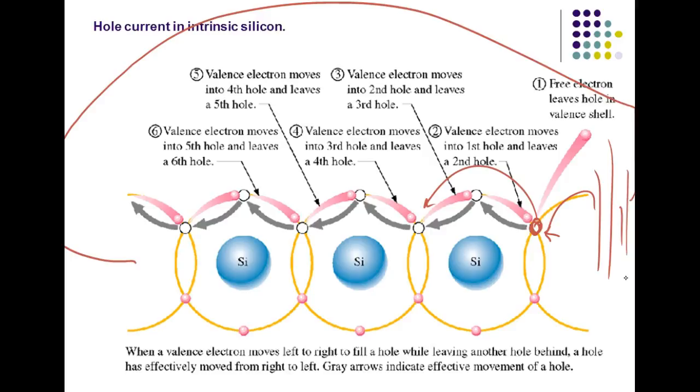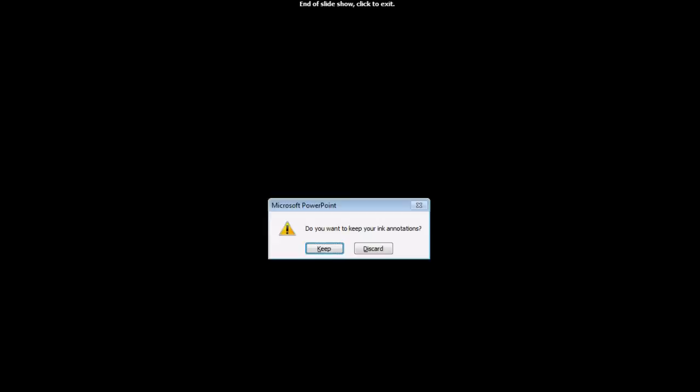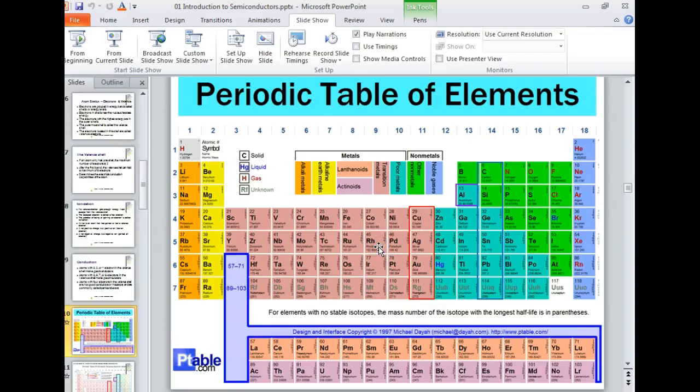The problem with this is that if we come up here and heat it up, what happens to semiconductors? It operates opposite from conductors. Metals, when you heat them up, their resistance goes up. Semiconductors, when we heat them, the resistance goes down. Because it's just like most things. Metals are a little strange, but most things, when you heat them up, the atoms become more active. And they become more active, more electrons can move up into that conduction band where they can be moved.